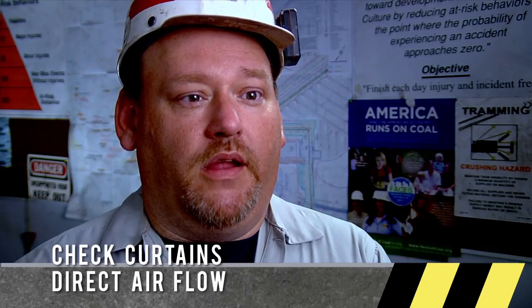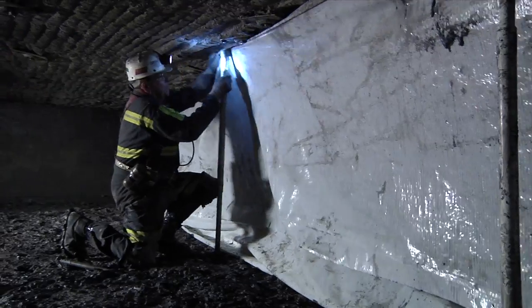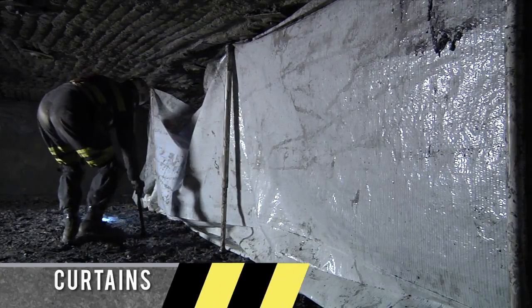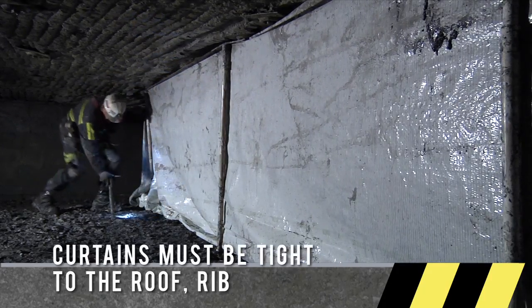The purpose of a check curtain is to direct the air to where we need it to be in the mine. It can either be a permanent or a temporary support, temporary being where we're going to put a wall up. Before we put a brattice wall up, we put a check curtain up to direct the air. Problems with a check curtain, 99% of the time, are that they are not installed properly. They're loose, letting air pass through them, or they fall down and no one puts them back up into place.